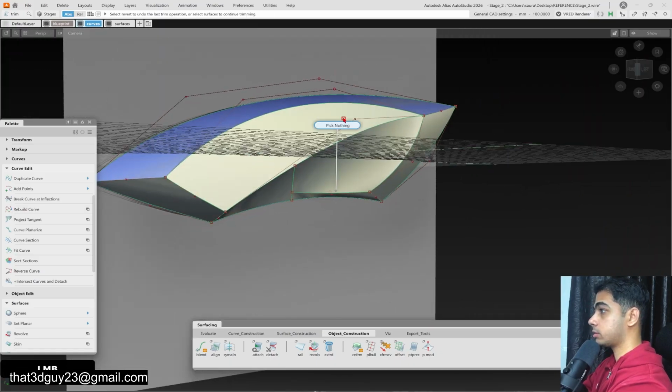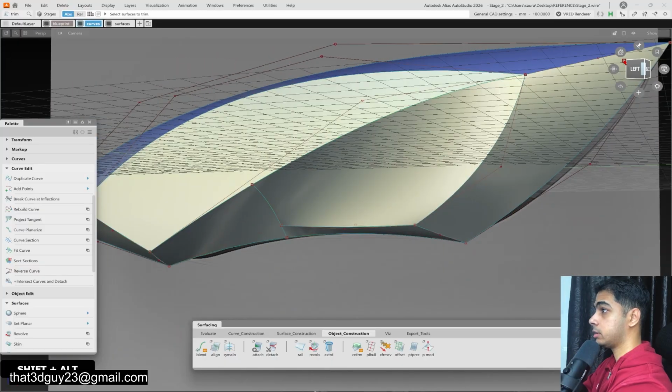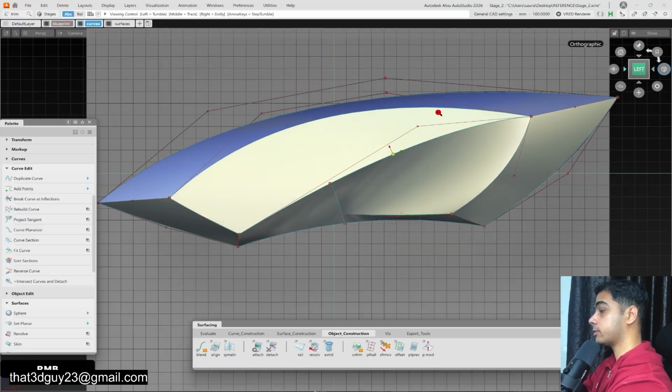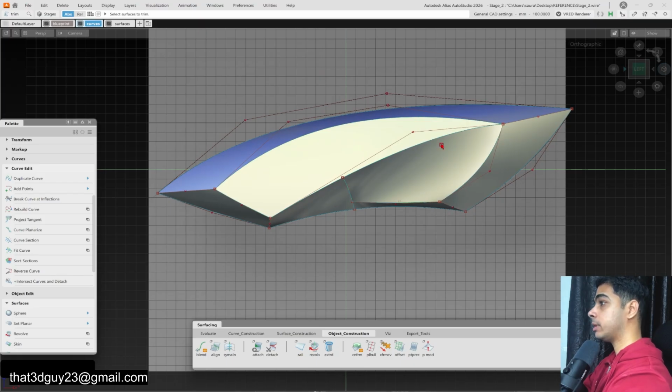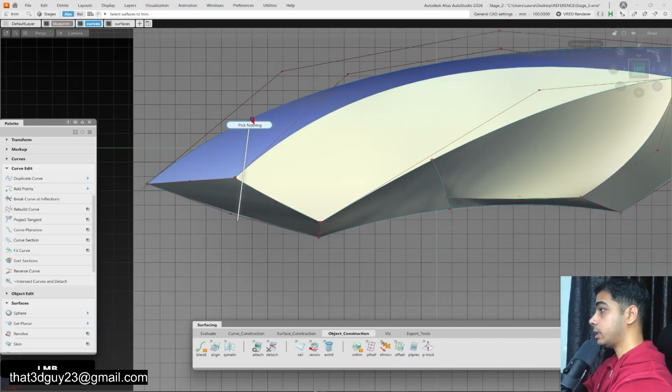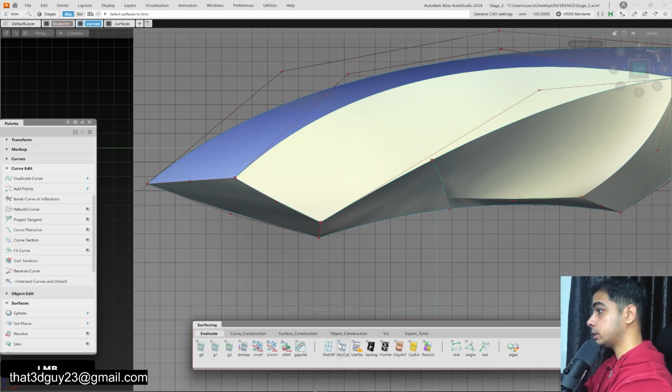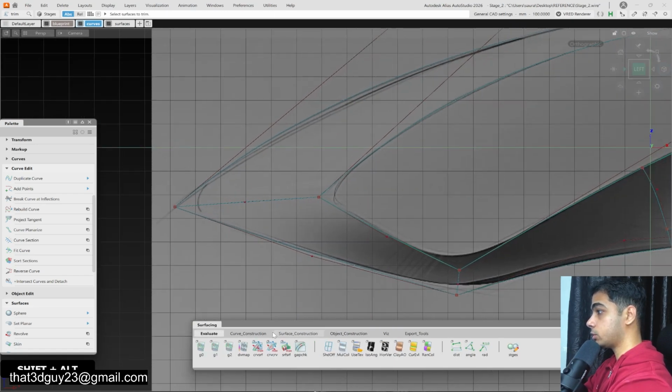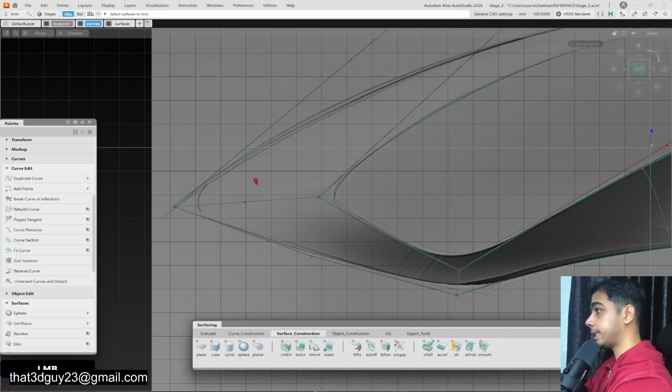It's just about filleting it, and that's where I would say a lot of people mess up. So this is something that we'll be working on now. Let's make the simple ones first. What I would also do is, there are two options. I can either extrude it back, which is good because obviously I'll have the originality of the surfaces.